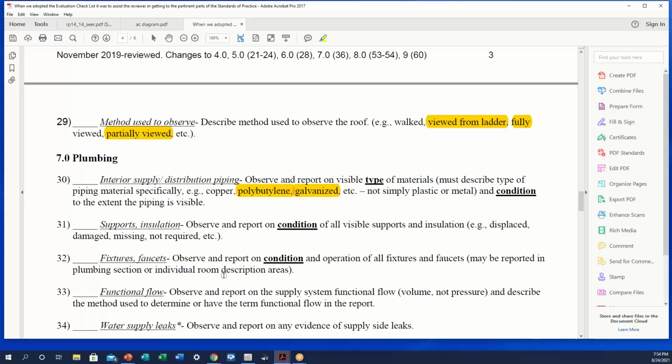Okay? I thought they did that so you could see it. No, the requirement for PEX is not to be exposed to any UV light. That's number one. Well, the attic is enclosed. Well, I can almost explain to you, if we went up there, the ventilation requirements for gable end venting, there is some light up in there. So some aren't, but either way, if it's a fully insulated space, we're fine. But I just make a note of it because I have to, because when we had that freezing weather in the 19 degrees, pipes were freezing up in attics all the time because they were up outside of the insulation.